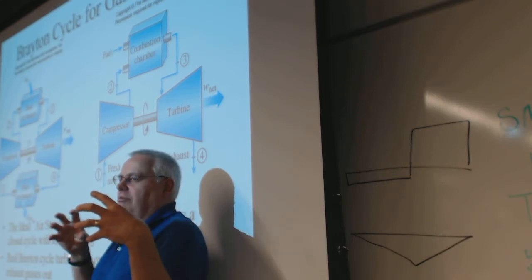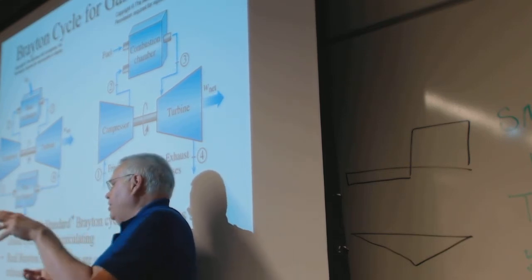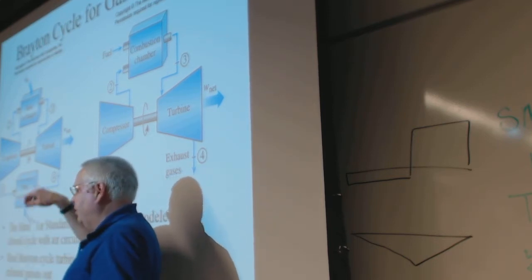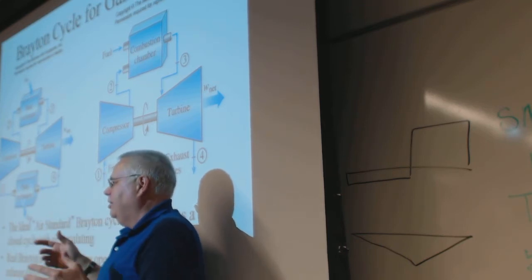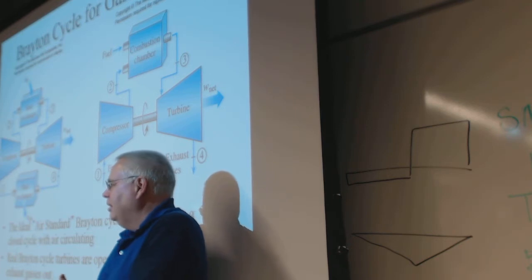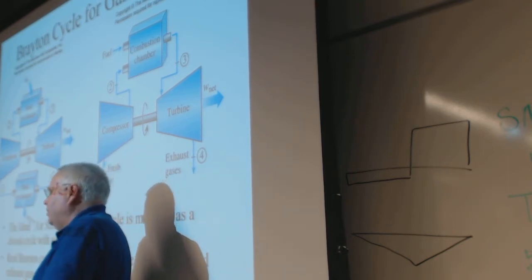They used the inlet to generate high pressure air, bled off what the engine didn't need, reintroduced it around the afterburner, and that jacked up the afterburner pressure. Messing around with the inlet became like 30% of the recapturing of kinetic energy. By using the inlet as the compressor, basically?